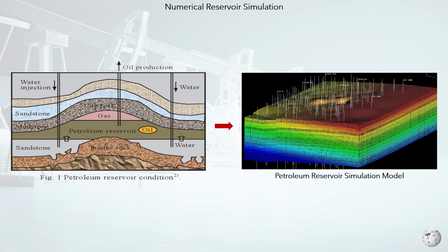Numerical reservoir simulation is an area of reservoir engineering, in which mathematical models are used to predict the flow of fluids, typically oil, water, and gas, through porous media. Traditional finite difference simulators dominate both theoretical and practical work in reservoir simulation. Conventional physical simulation is underpinned by three physical concepts: conservation of mass, isothermal fluid phase behavior, and the Darcy approximation of fluid flow through porous media. But it should be noted that finite element models are a higher precision alternative, and as expected, of higher computational cost.